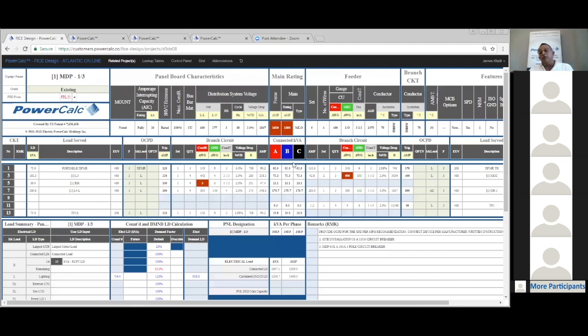So they set up the transformer sizes, all of them at 112 kVA. Now, once they did that, it also affected the construction. According to the NEC, if the transformer is actually over 75 kVA, the room that houses that transformer has to be designed with a fire rating of 2 hours.